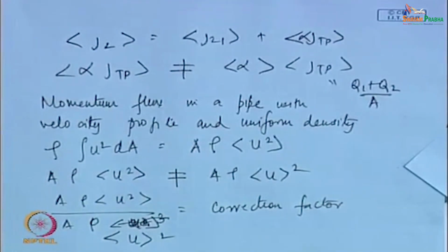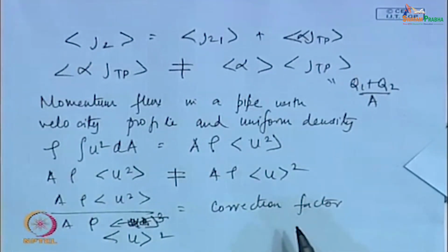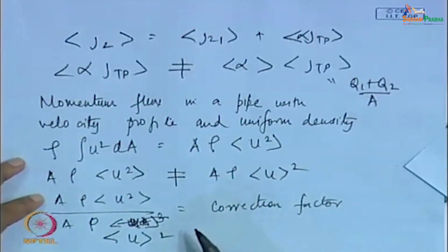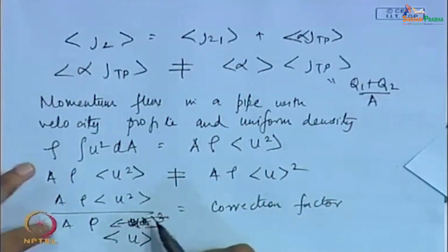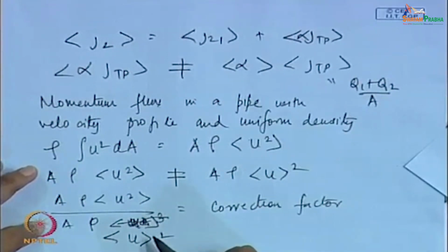It is all right. So, usually what is the concept of single phase flows? In single phase flows we find that more or less the ratio of these is not very far from unity. And for truly one dimensional case they become unity, because for truly one dimensional case the velocity is the same for all points in the cross section.